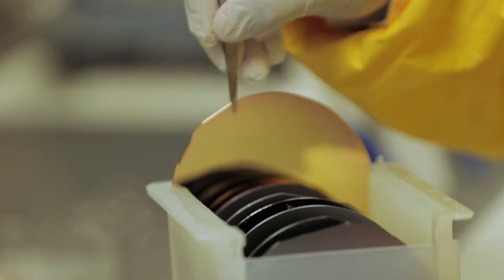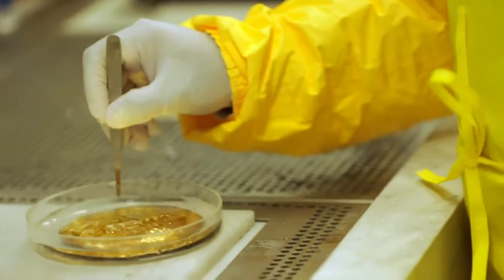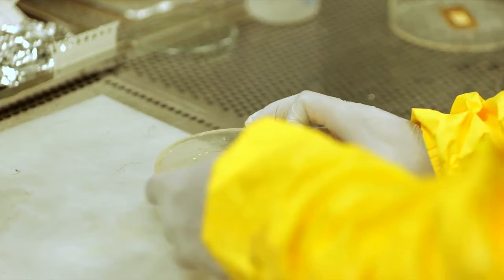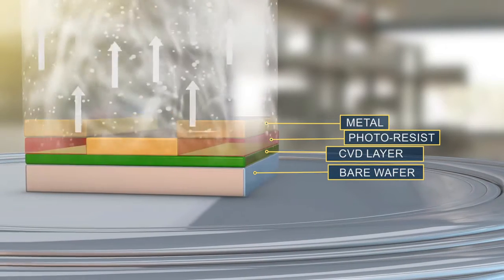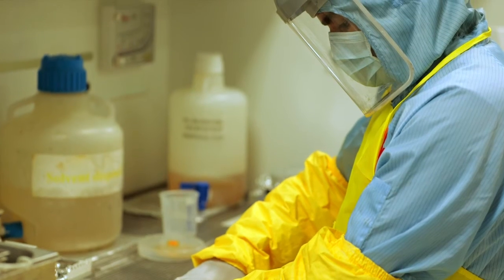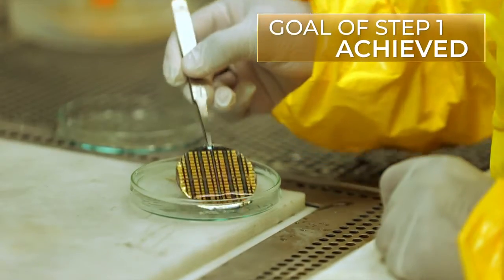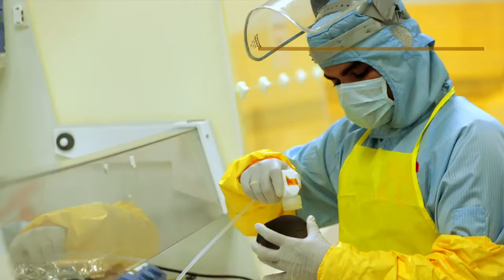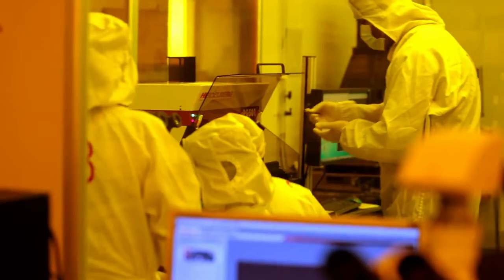The wafer is now subjected to a process called lift-off to get rid of the photoresist-coated metal. It is dipped in a solvent that dissolves the photoresist and in the process removes or lifts off the metal on top of it. The metal that is deposited on the wafer surface stays in the form of the pattern that was desired. The first mask step we had embarked on, what appears to be a long time ago, is now over. Devices require that other patterns be transferred, but with a specific relation to the first one.